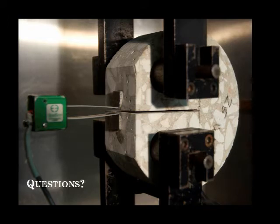Yes, but in general, the direction. Oh, yeah. And in the SEB, they are not in one direction. You are applying the load vertically and you are measuring the CMOD like this. So it may have some effect. Maybe what you are seeing is due to that reason. Yeah, that's also because when you apply the load to the beam, there's more of a dispersion of the applied load and applied stress, which would lead to, theoretically, a higher K1 value.